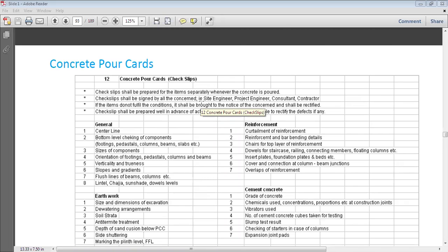And that is the first difficulty, as I said earlier, the hindrances, which we already discussed yesterday. That is the first difficulty you are going to face: converting the drawing paper plan on site, that is, on the actual field. From which point are you going to begin your work? For that, always remember we are going to set the benchmark where you take the RLs of all different levels.